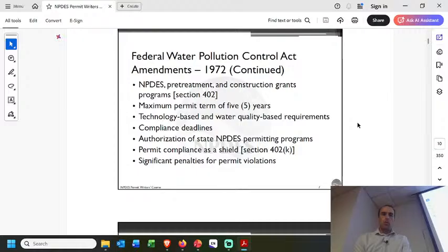Okay, moving on, we have this NPDES permitting system. There is a parallel one for groundwater. I don't know as much about that. That wasn't where I was working, but there was a similar system aimed at protecting our groundwater resources with similar treatments required, because you can potentially discharge water to the ground. The permits, just a few general topical things. They can only be up to 5 years, and realistically, any of the big ones or complicated ones are renewed every year and reevaluated every year.